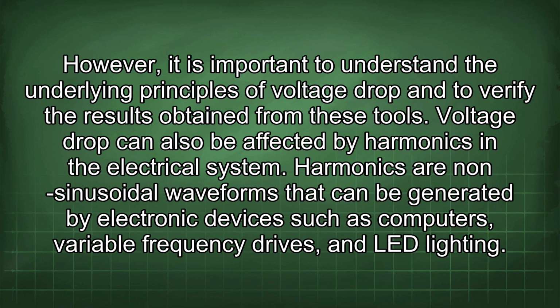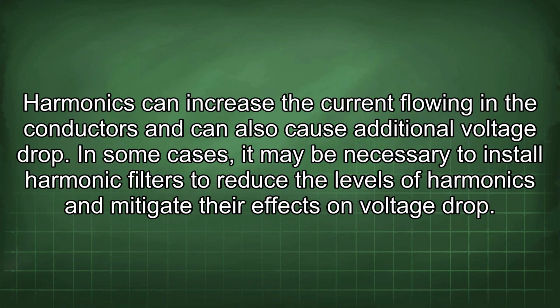Voltage drop can also be affected by harmonics in the electrical system. Harmonics are non-sinusoidal waveforms that can be generated by electronic devices such as computers, variable frequency drives, and LED lighting. Harmonics can increase the current flowing in the conductors and can also cause additional voltage drop. In some cases, it may be necessary to install harmonic filters to reduce the levels of harmonics and mitigate their